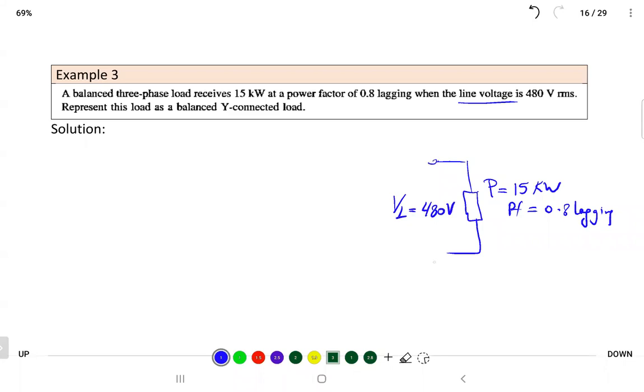By the way, all the equations I used in the previous example assume that the values are in root mean square, that the voltage 110 was root mean square. So you have to pay attention to that. All equations are based on root mean square values. And the angle of the voltage is not given. We always assume it is angle 0, the reference. It doesn't hurt.